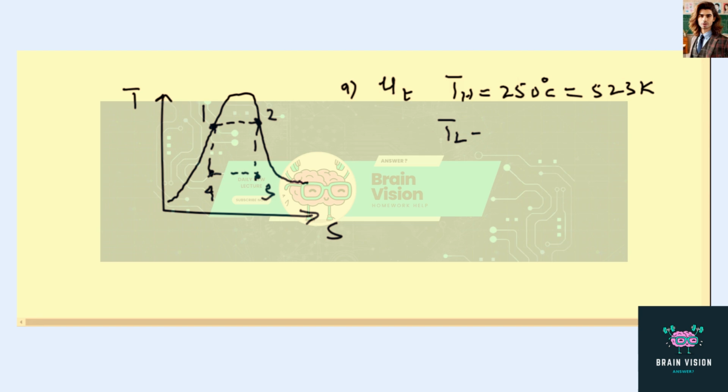And low temperature is equal to 60.1 degrees Celsius, and that is equal to 333.1 Kelvin. And now thermal efficiency is equal to 1 minus low temperature divided by high temperature.